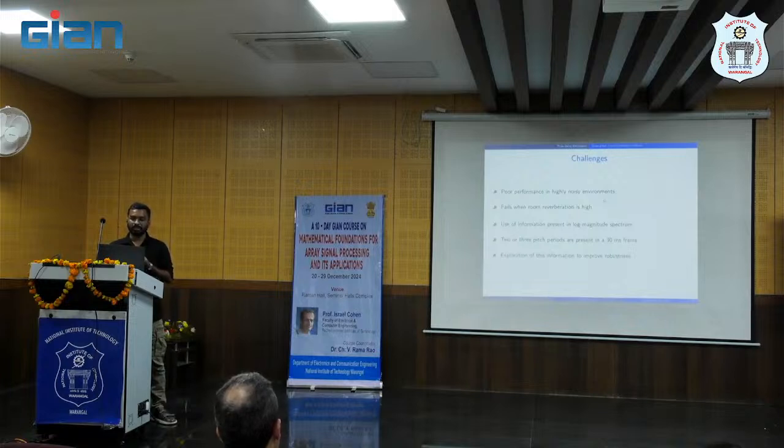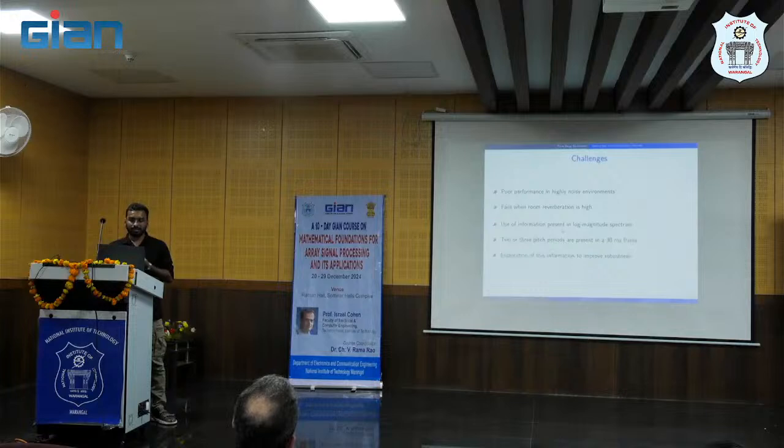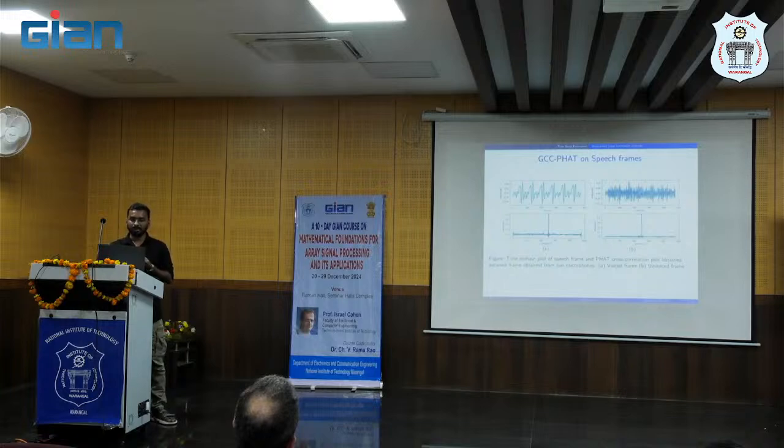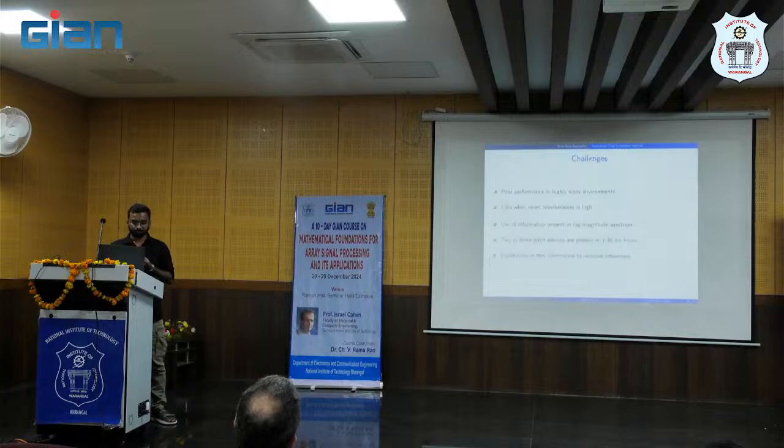The challenge is that GCC-PHAT or classical cross correlation is poor in highly noisy environments. In moderately noisy and noisy environments it performs well, but it fails when room reverberation is high. So we thought, can we use the information present in the log magnitude spectrum, since the voiced and the unvoiced frames have different characteristics. Our analysis is mostly on the voiced frame.